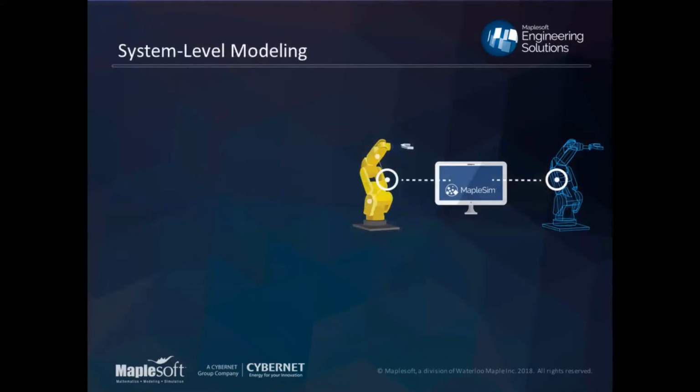So what is system level modeling? Sometimes referred to as 1D modeling, it can also include 3D multibody dynamics, but that isn't necessarily what we'll be getting into today. This is different than models that you would make in FEA or CFD programs, which vary not only in time, but in spatial dimensions. System level modeling is a complementary process to these other modeling techniques. In a design process, it's generally a mix of discrete and continuous systems spanning multiple physical domains.